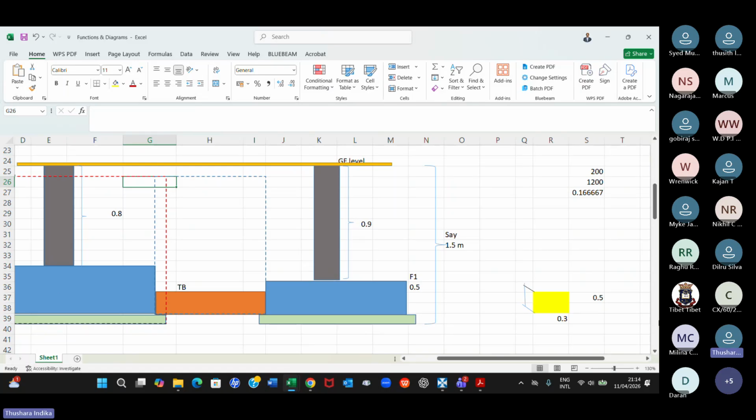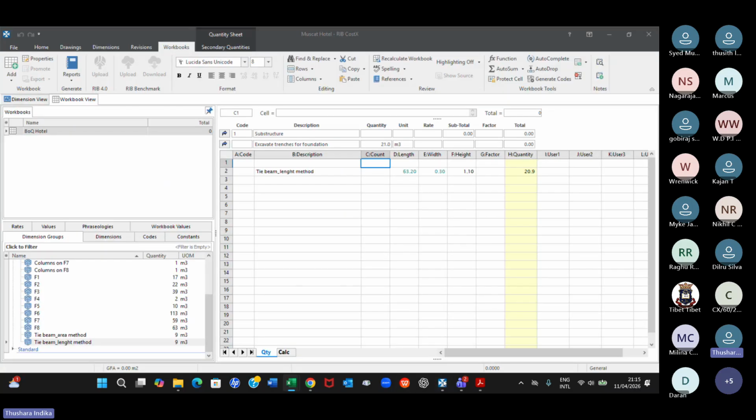Duplication is, one is 0.3. The length, if you take, this is 100, right? So each plinth beam, you have an overlap of 100 millimeter, both sides, right? Both sides you have 100 millimeter, width is 0.3. You can deduct that much of amount, volume, into 1.2 height. So you remove the duplication. So what I'm trying to do is I'm using this one here, and I'm going to deduct the overlap.